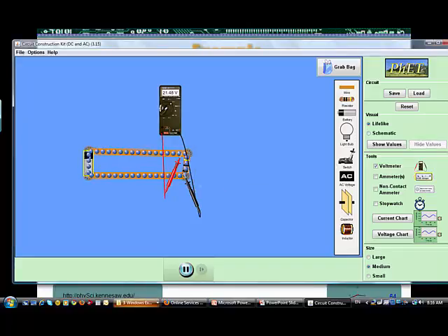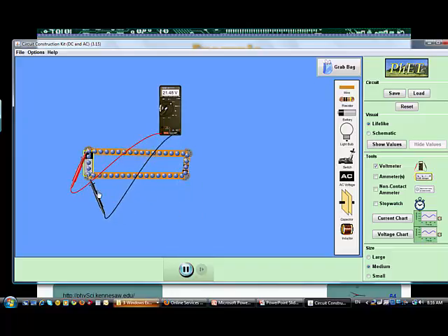Now if it is 1 ohm, look at the voltage difference across the battery. It's 21.48. It is not the 24 volts that we had initially. Let's disconnect this. I'm going to right click here, split junction. Now look what I read, 24 volts.